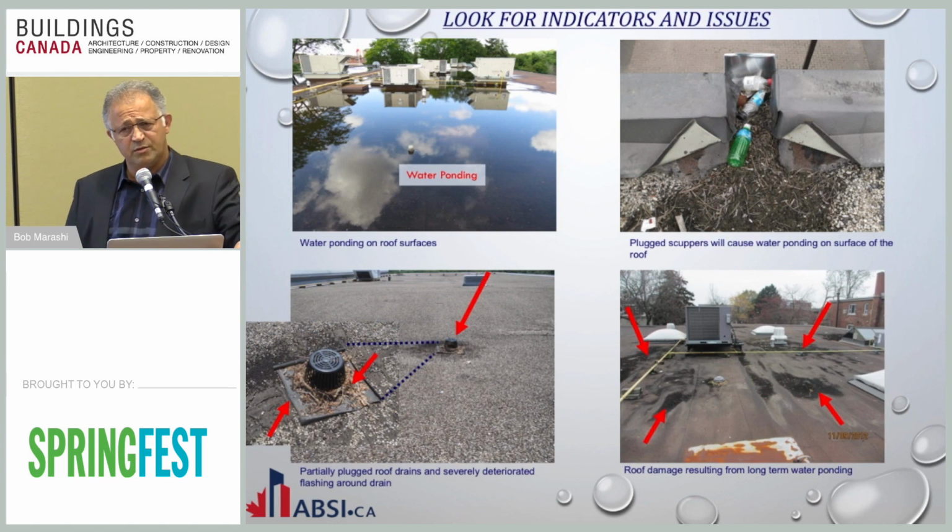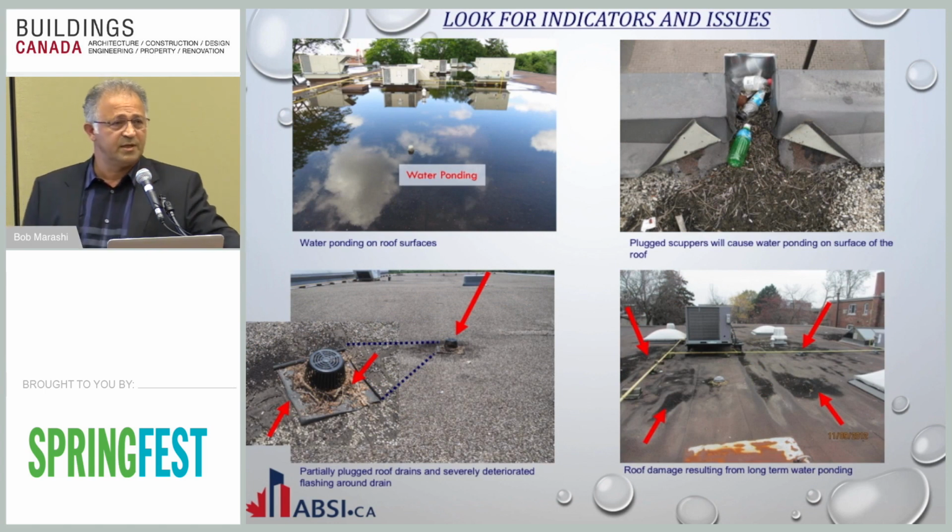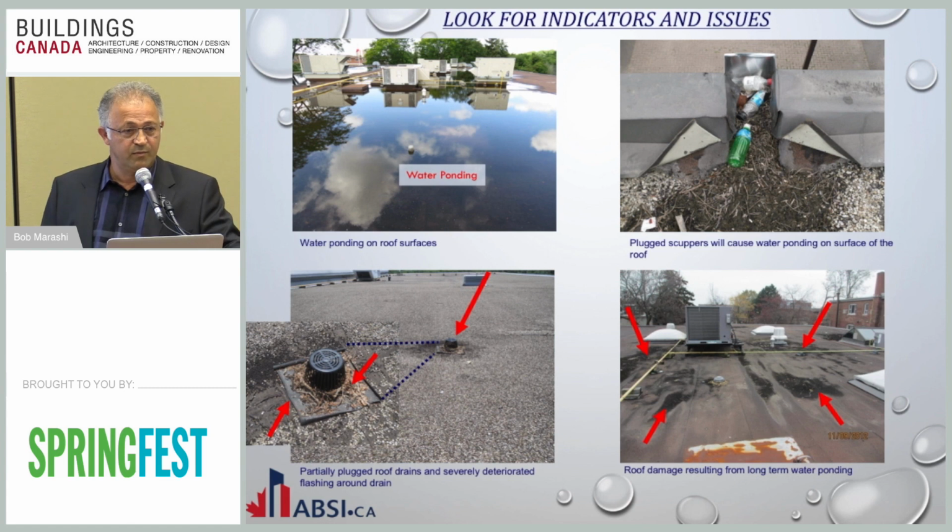Drainage is a huge issue on roofs. Rule of thumb says two days of water ponding on the roof. After that, you need to do something about it. Well, that ponding in the image is more than two days. It's a swimming pool on the roof. And it's only there because the drains are plugged with tree debris and all the other garbage.